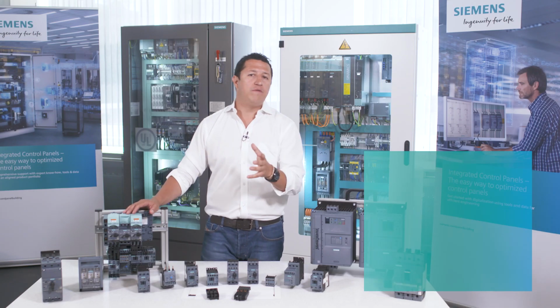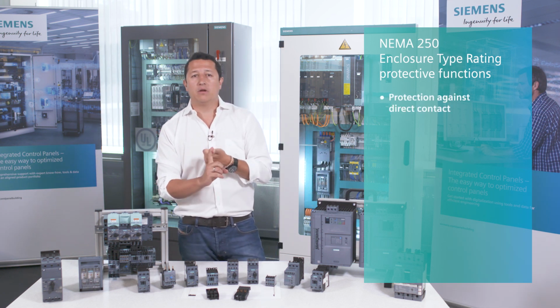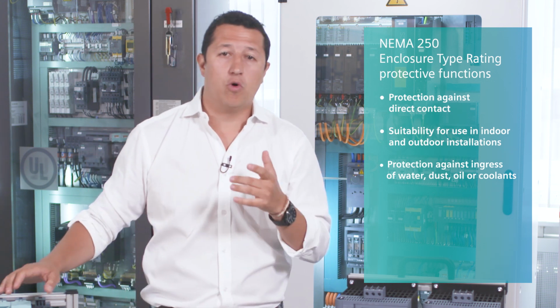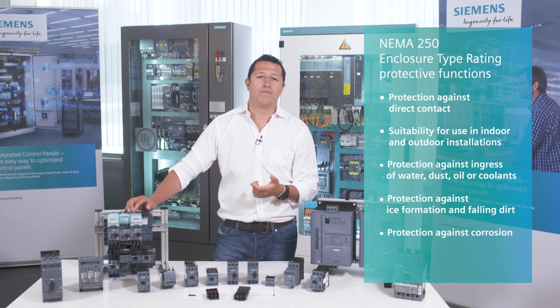A NEMA 250 enclosure type rating indicates numerous protective functions, such as protection against direct contact, suitability for use in indoor and outdoor installations, protection against ingress of water, dust, oil or coolants, and protection against ice formation and falling dirt. Also, protection against corrosion.